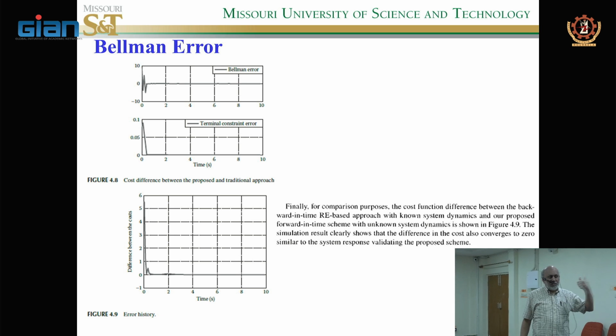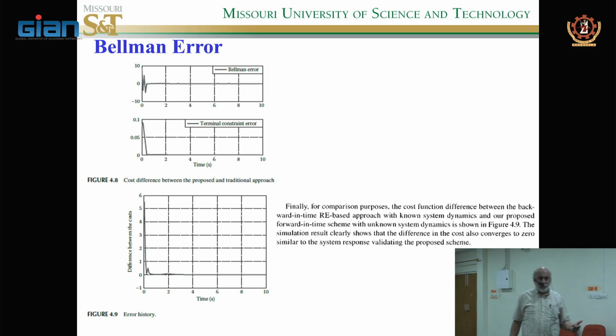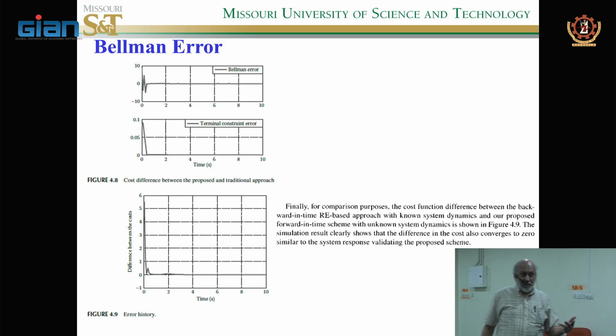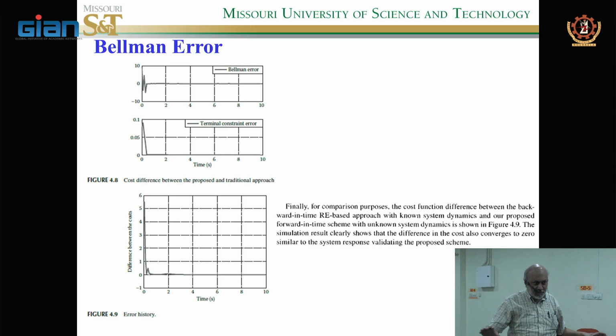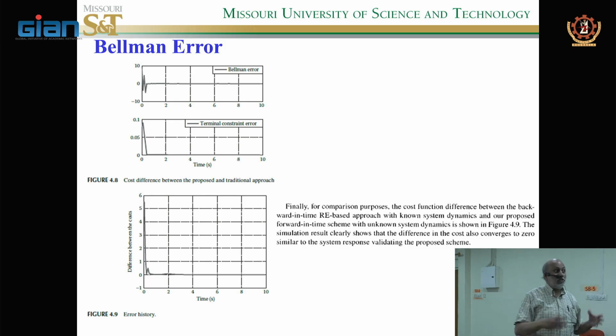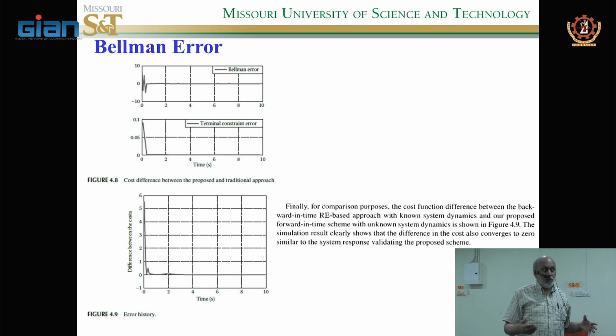So we studied what quantization is, what static quantization is, and how it affects the control input and the state, right? We need 2 quantizers, one for the state to controller, and the other one for the controller to the actuator. And we saw how it changes the mathematics in the control input. That's very critical. See, that's why papers get published. You have to have the mathematics to show why it affects and why it is important.